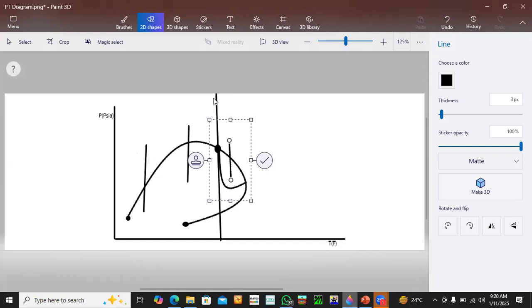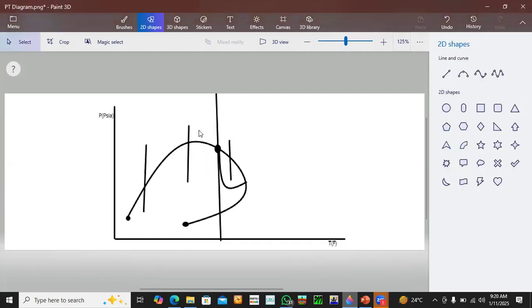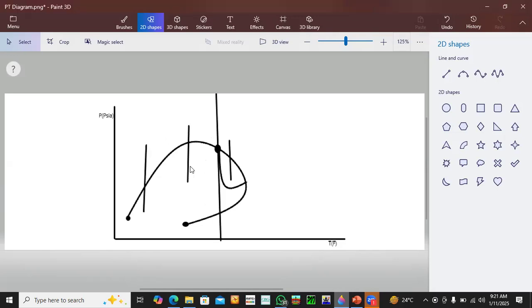Volatile oil usually ranges between 26 degrees API gravity to around 45 degrees, and is usually called the light crude. Its formation volume factor ranges between 1.2 reservoir barrel per stock tank barrel to 2.5, and it has an intermediate gas oil ratio, not like that of black oil. Black oil is usually within 150 to about 800, but the volatile oil is usually 1,000 and above, like 1,000 to 2,000 approximately, scf per STB.